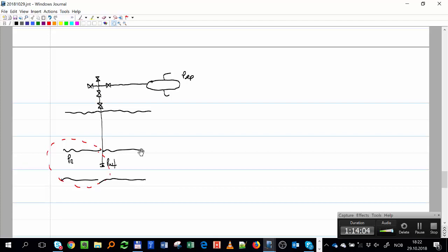Okay? So how is the curve going to look like if I plot PWF versus Q? Okay, like this one. We don't know yet about equations, but if you use the same analogy that we use for the pipe, it should look something like that, right? And what is the point 0 here? Reservoir pressure, right? If I have no flow, I just get reservoir pressure, the same pressure around the reservoir.